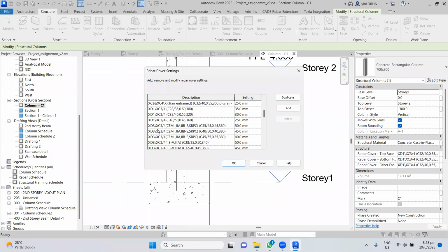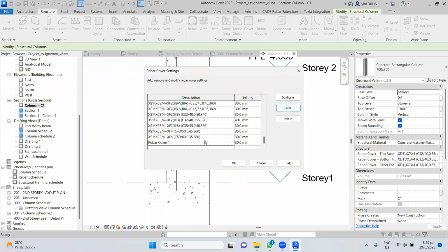You know, right? In Eurocode, they define the exposure condition XC1, XC2, XC3, XD1, and so on, right? So if you are not familiar, if you want a custom one, right, for your own project, you can add it on. Let's say the column, right? I'm going to maintain the consistent cover for all columns. For let's say 40 mm. So I maintain 40 mm, right? For beam, for example, let's say beam, right? Beam, normally we may have two different covers, beam bottom one cover, beam top another cover, right?